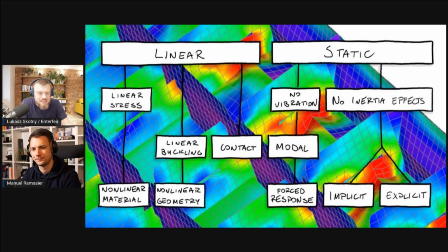Yes. When it comes to dynamics, everything takes part. And suddenly, you may not have modeled things that will be important in your modal analysis, right? And then you're doing the modal analysis and essentially hoping that your model is good enough. Yeah. And I have a friend who has a PhD in dynamics, and I asked him once, what would be the best approach? And he would say, build it and then dampen whatever shakes.